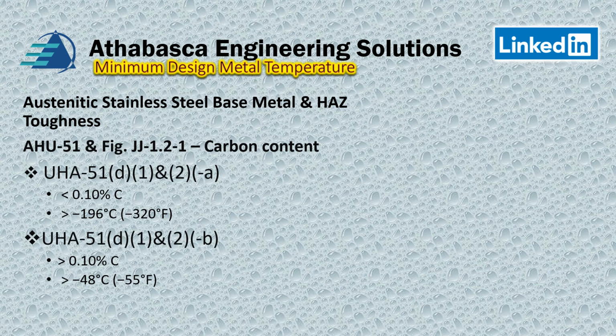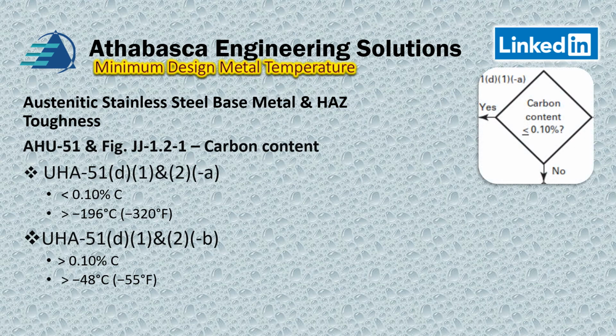And then there's another case where you're the opposite. If you've got a higher carbon content, then you're basically looking at a higher MDMT. So the graph will show something like this, and basically you've got yes, you proceed that way if your carbon content is less than that, and no, you would go the other way.